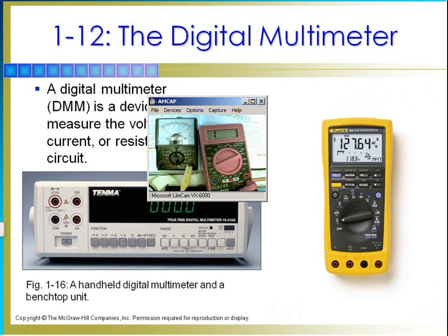And one is not necessarily better than the other. They both have their uses from different times. So they're both set for resistance right now. And just for instance, I'll short out my multimeter here, my analog, and you can see immediate needle movement, an immediate reaction as soon as I touch it up.